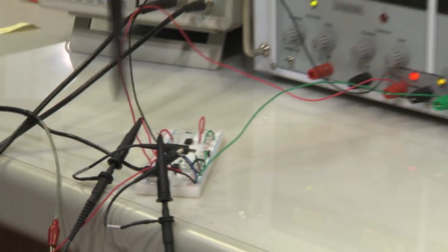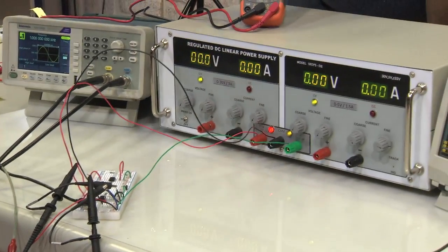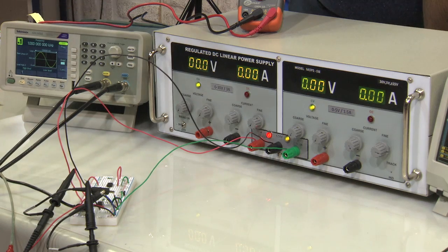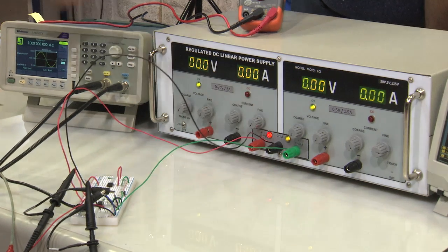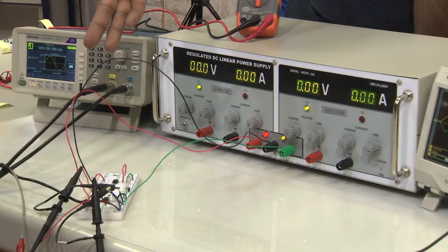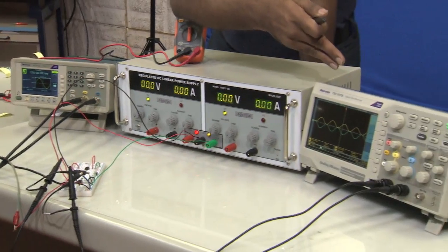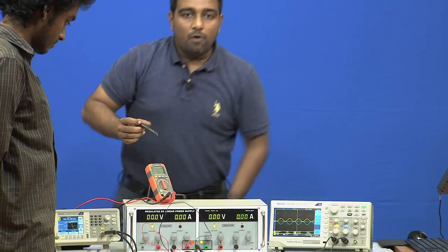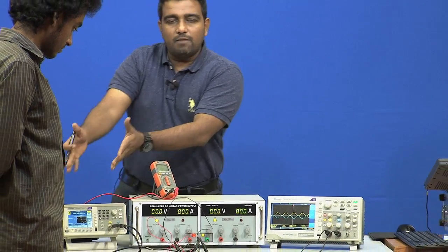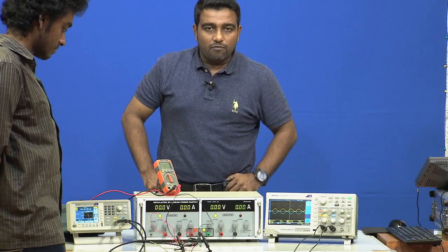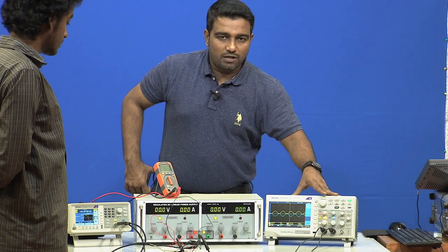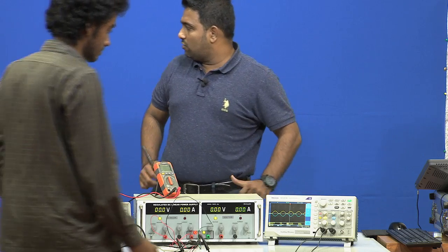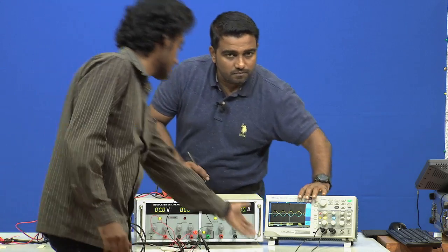Because of the probes it looks complicated, but it is very simple. One red wire from the frequency generator is the signal to the inverting input, black to the ground, and from the output one signal goes to the oscilloscope, ground connected to the ground. It is extremely simple. Now when we have applied the input signal, which is 1 volt peak to peak, 1 kilohertz, what is the output? That we have to see. So if you focus on the oscilloscope, what do we see here? Can you please focus on the oscilloscope?